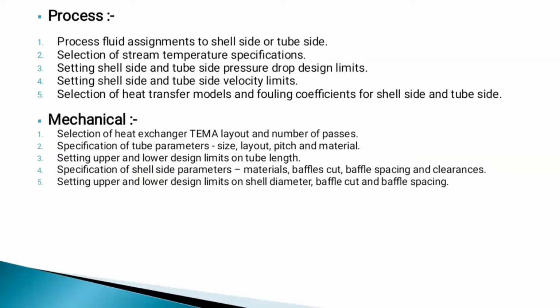The mechanical design of the shell and tube heat exchanger: the selection of heat exchanger TEMA layout and number of passes; the specification of tube parameters, size, layout, pitch and materials; and the setting of upper and lower design limits on tube length.